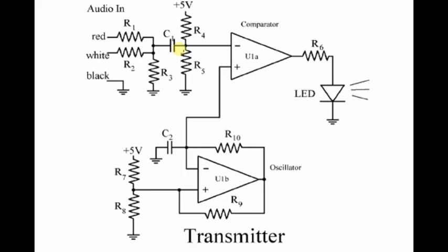Through this divider, this capacitor helped smooth out the signal. And this plus 5 volts and divider here added a DC offset to our signal to better compare with our oscillator. Our oscillator circuit used this plus 5 DC volts through a divider and then into this op amp.